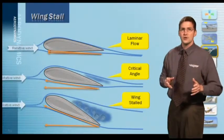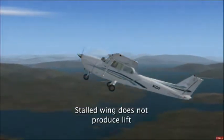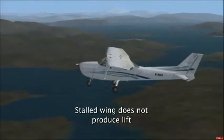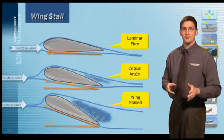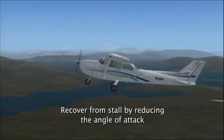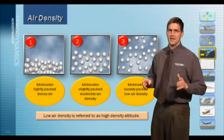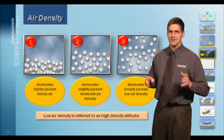Lift is no longer generated because the critical angle of attack has been exceeded. A stalled wing is not producing any lift. To recover from this, reduce the angle of attack and it will begin to produce lift again. Stalls occur at the same critical angle of attack regardless of altitude.